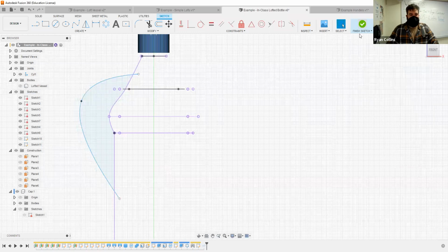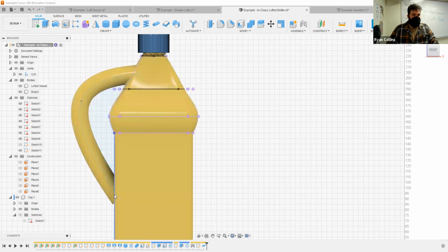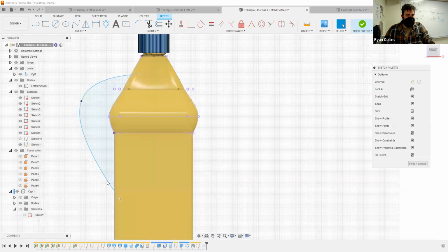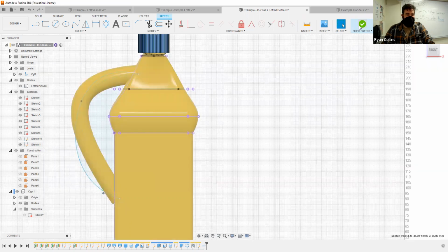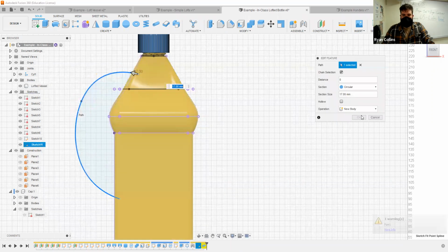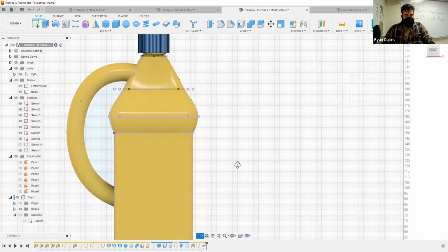Select OK, let it recalculate. Now, when I unhide the body, it's kind of moved in there. So the pipe tool is not going to be the best option. The other option, of course, is also editing that sketch and just playing with your handlebars. If you rotate that in a little bit, you're going to get a better match. Now, why didn't that work? Pipe, edit feature. There you go. Why didn't that recalculate? That was weird. Okay, don't know why that happened, but there you go.